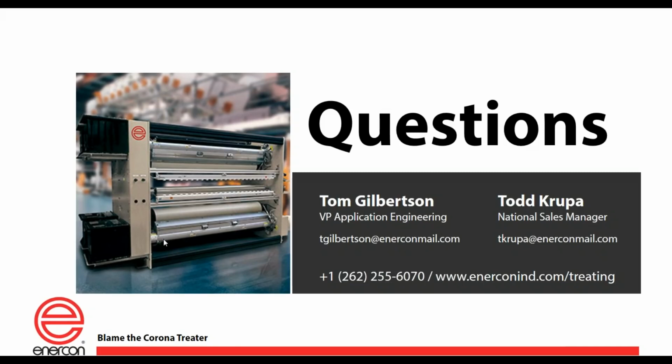We've got a customer that is going to be running polystyrene, and they haven't run it before. Can you speak towards its receptiveness to corona treating? Well, polystyrene, yeah. If I go in the order from easy to hard in film receptiveness to corona, styrenics, nylons, and polyesters typically respond the easiest to a corona treater.